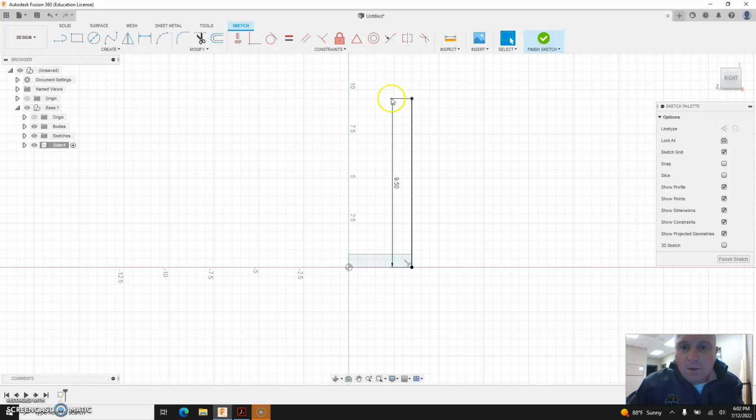All right. From that 9.5, I'll get my line tool over again, and I'm going to come over to the left of that, and from our drawing, it goes over 3/4 of an inch. So I'll type in the 3/4 and hit enter again. Then I'm going to select the escape key on my keyboard, because I don't know exactly how this angle is going to work out right now from my drawing, so I'm going to start from this point and work the other way. So I'll again select the line tool. I'm going to go from here back to our origin, and that creates the base of it.